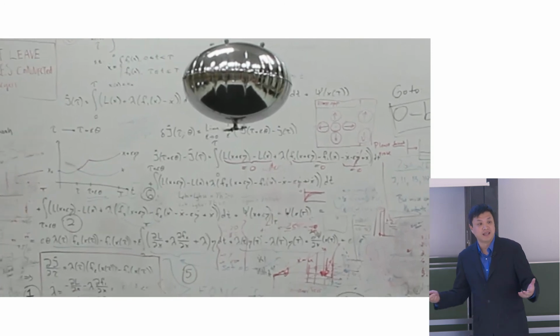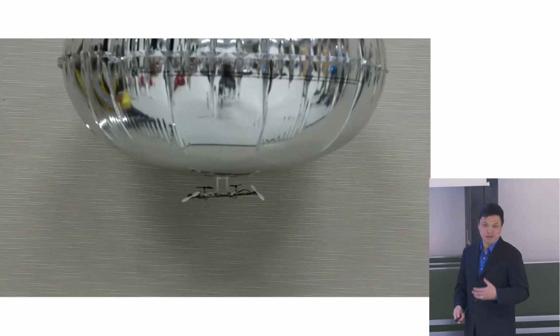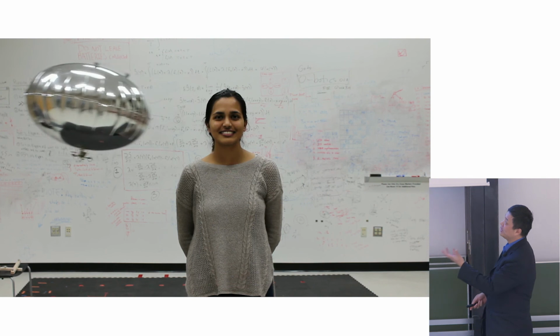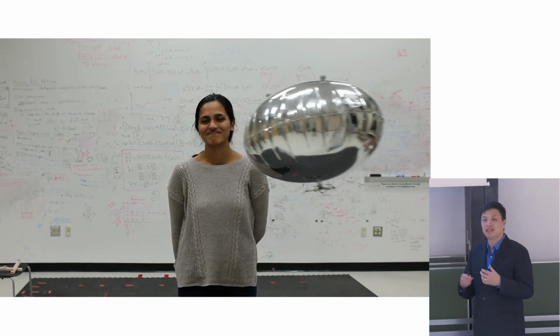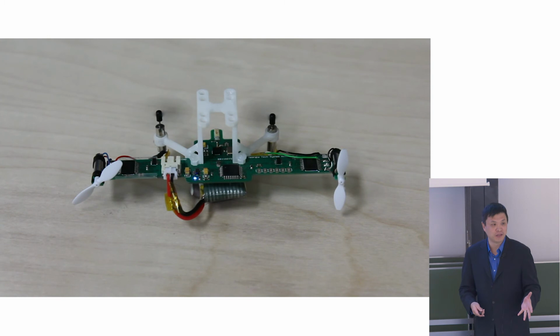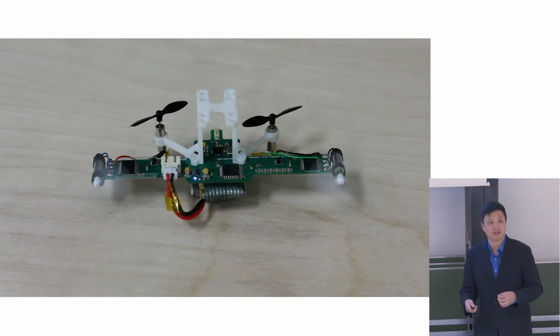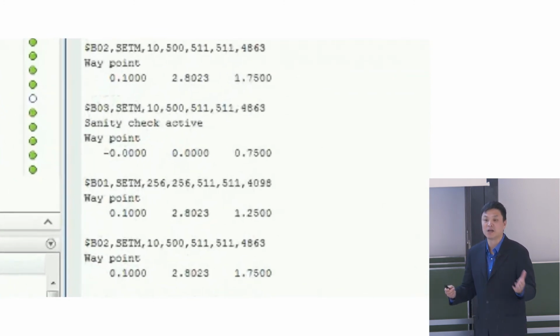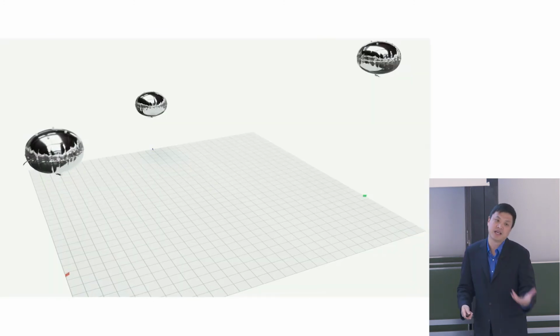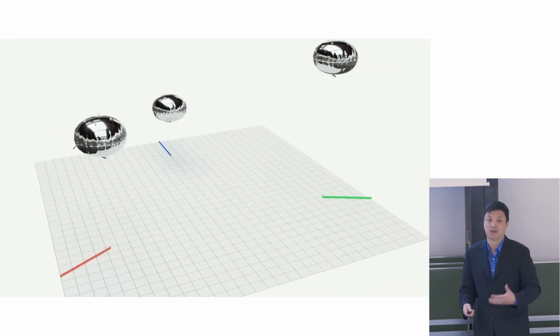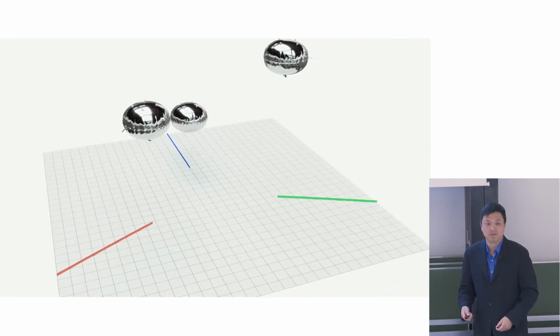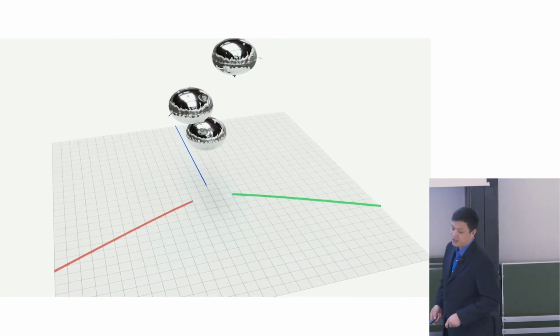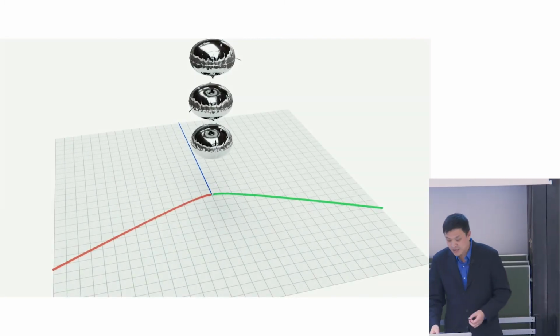And we call this flying underwater vehicles because we do some work in underwater vehicles. But this is really robotic blimps. They have really nice properties, okay? They're very friendly to humans, very safe to play with. And another thing is they fly for a long time, so they fly 2 hours per charge. So that's good to implement all this distributed sensing environment because sometimes you need longer flight time. If you use drones, they're not safe to humans. And also, they only run about 15 minutes per charge. So these are some of the advantages that this blimp has.